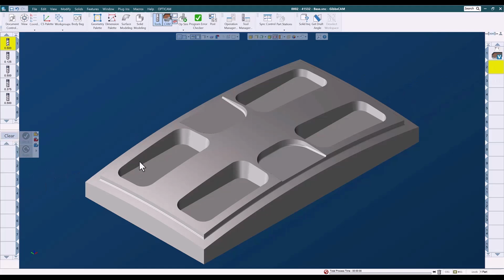I think the next thing I'm going to deal with is going to be the 7.5 degree walls on these 4 pockets. There are a few ways that I could approach that. The main thing that I want is minimal retracts, minimal times the tool pulls off the finished surface. So I want to start cutting this surface or this edge here and finish cutting this edge, but with a spiral down. So my passes are going to be closer together on the short side than on the long side.